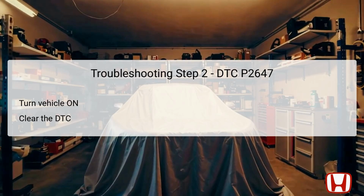If the test results indicate that the system is functioning properly, this could suggest that the DTC may have been an intermittent failure, leading the technician to inspect for poor connections or loose terminals related to the rocker arm oil pressure switch and the PCM.